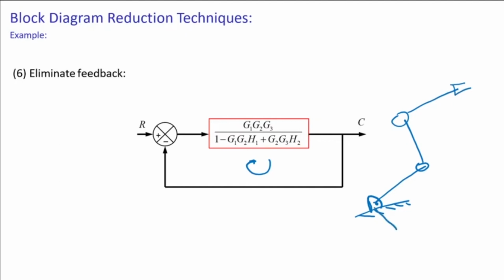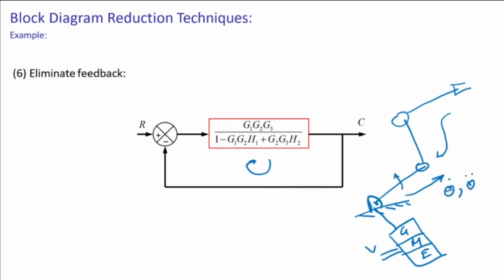Now as far as the controller is concerned, the controller is only controlling the motor. There's an encoder and gear in front, so it's controlling the voltage to the motor. And the controller does not know what is happening on any other joint. So this is what we call independent joint control. But when the robot is moving, the velocities and accelerations are propagating. If this link moves with a particular velocity, the second link is going to have its own velocity plus the velocity of the previous link, and this will start going forward. Similarly, if there is a force there, this force will come backwards.